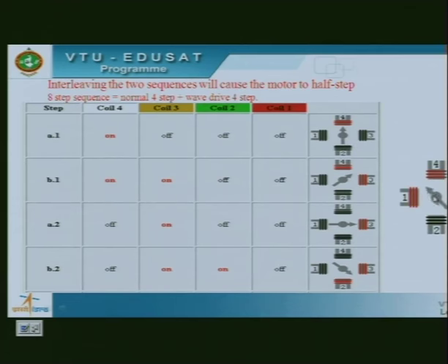So, you can see the movement here, how clearly when a single coil is energized it will point to that coil, and when 2 coils are energized it will take an in-between position between them. Similarly, in the third step this coil is energized, only that, in the fourth in between these 2. So, that is how it continues. You can see the positions shown here.